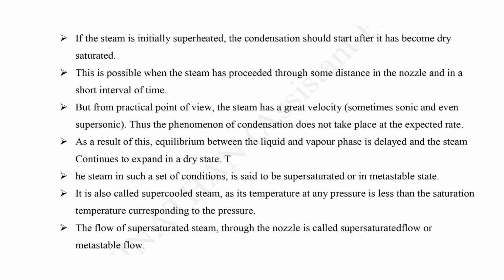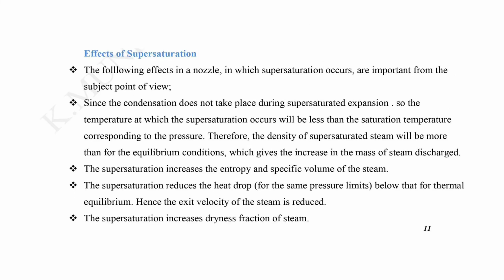It is also called supercooled steam as its temperature at any pressure is less than the saturation temperature corresponding to the pressure. The flow of supersaturated steam through the nozzle is called supersaturated flow or metastable flow.